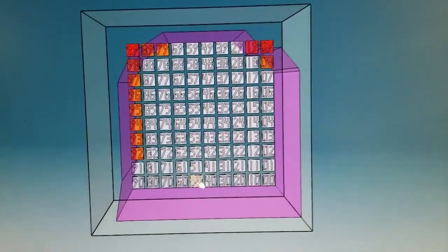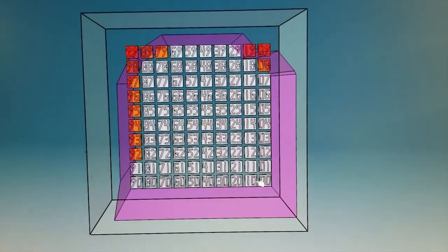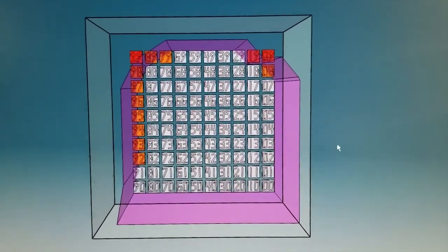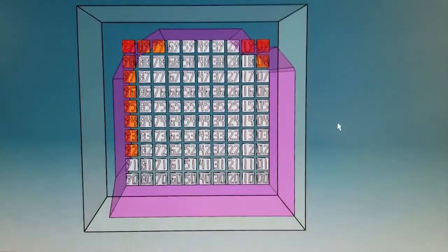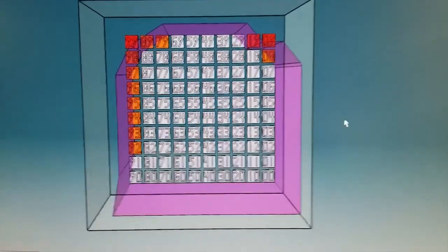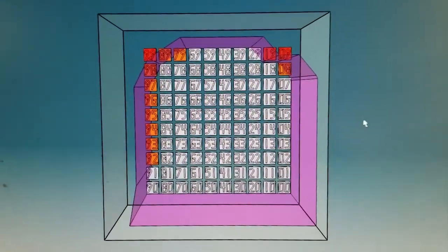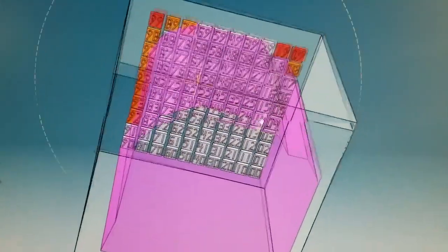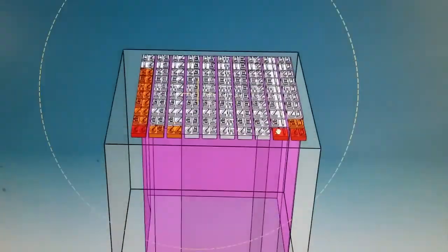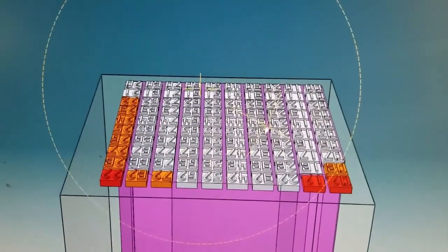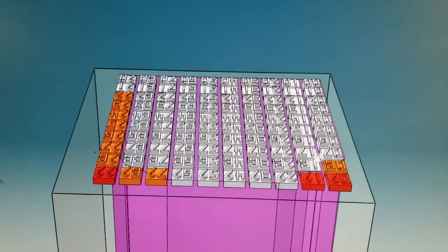the back side, the side that's along the back of the oven, sintered really well. I don't know if that's just because it has the electrical heater in the back, and that just transmits through the wall, and that allowed the geometry in the back to sinter really well. I don't know. But by using this grid, now I know what it can do.